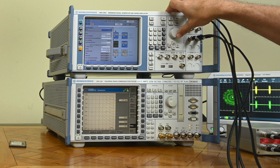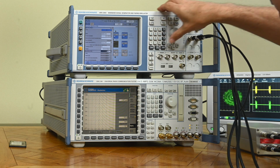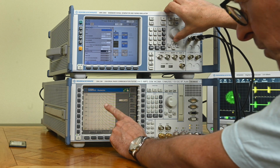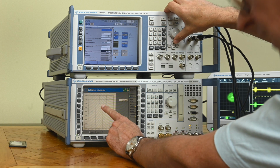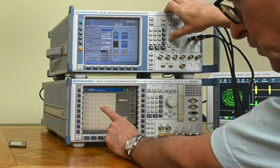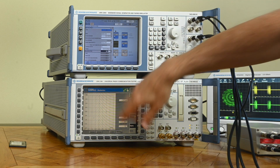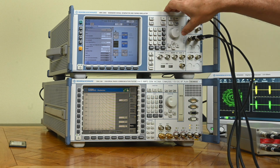So we get to this menu. We can turn it on. We don't see a real effect yet. But now I'm going to affect the signal to noise ratio, in steps of 1 dB. So I increase the amount of noise, and I hope you can see this at home. We see the noise around the constellation points getting very significant. It might be a bit hard to see on the YouTube videos. I'm reducing the noise, and I'm getting a little bit out of range of something, but the noise disappeared again. So we can use this for noise impairments.